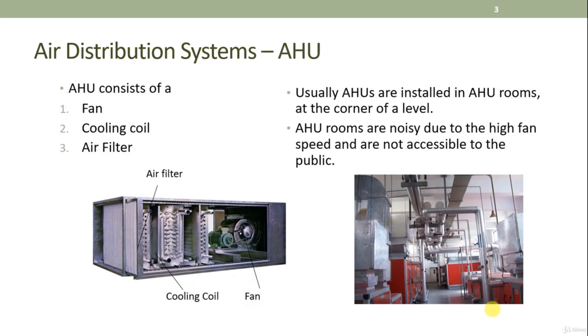So this is a typical looking AHU or air handling unit. In front here, there is the supply air fan, and usually the supply air duct is over here. So cold air actually is being pushed out from here and goes to the area that you need to cool down. And in front of the air fan, there's the cooling coil. So air will actually get treated over here, either get cooled down or heated up.